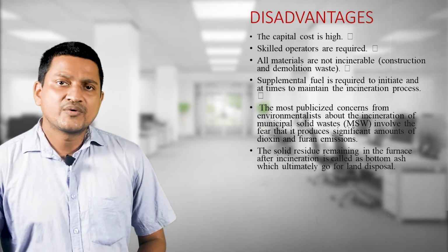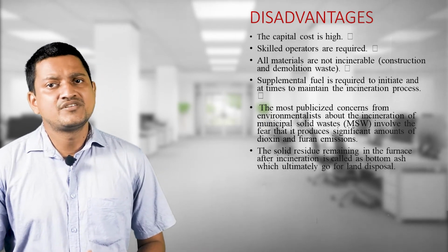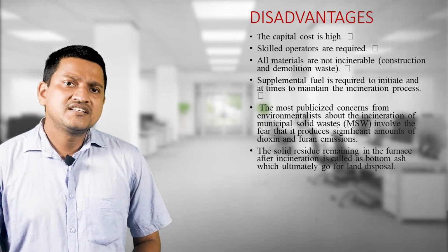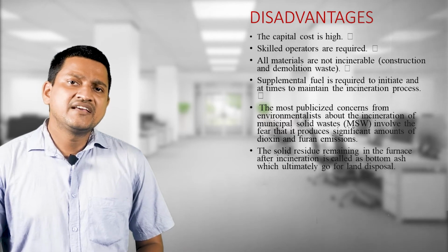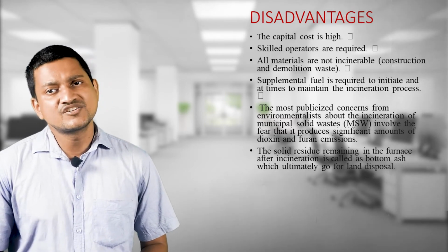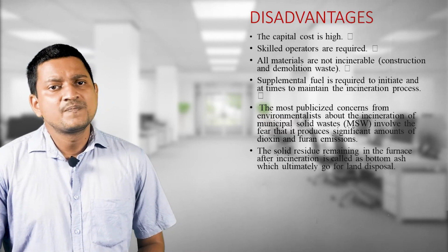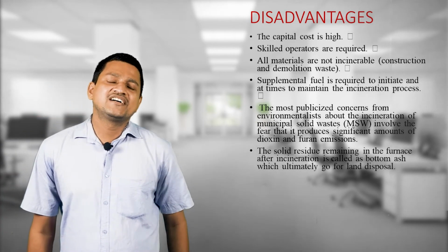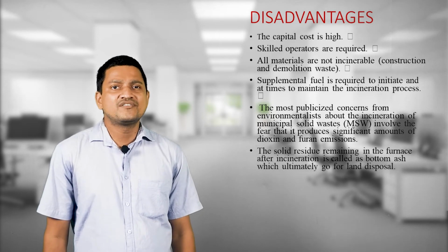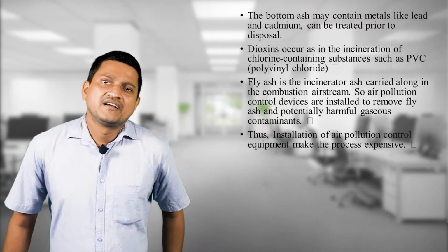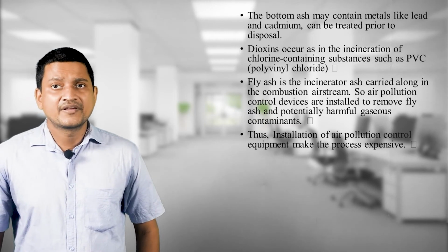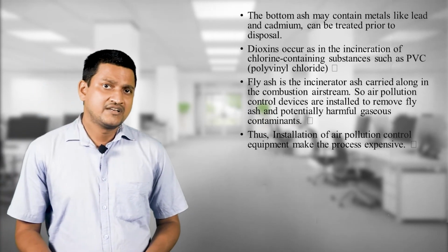Supplemental fuel is required at times to maintain the incineration process. The solid residue remaining in the furnace after incineration is called bottom ash, which ultimately goes for land disposal. That is another type of disadvantage of the incinerator. Bottom ash may contain metals like lead and cadmium, and can be treated prior to disposal.